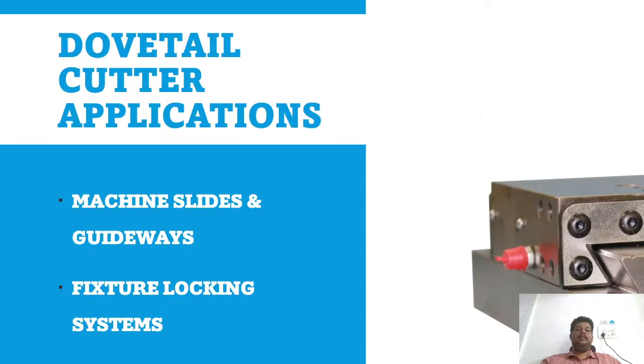Apart from that, the dovetail profiles are also used in fixtures where parts need to be locked securely, precision assemblies where alignment is very important, and even in tool holding mechanisms. So this is not just a cutting operation, it directly affects how parts move and how accurately they stay aligned. Whenever you see a design where components need to slide but not lift, you should always think of a dovetail.